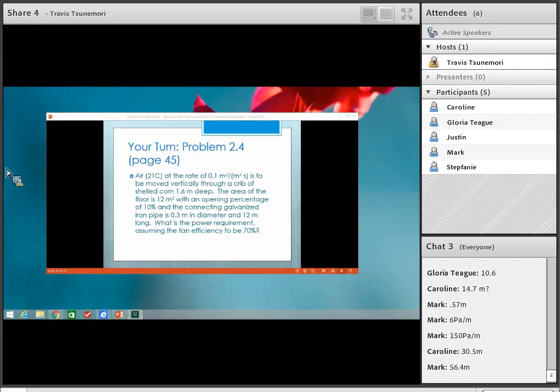So that's W times Q, which you had to calculate in the beginning, the volumetric flow rate through the system, and then rho G, and divide by the total efficiency, which is 0.7. And then figure out what units you have. So let me know when you've got a number for power, or if you have questions on what I just said.